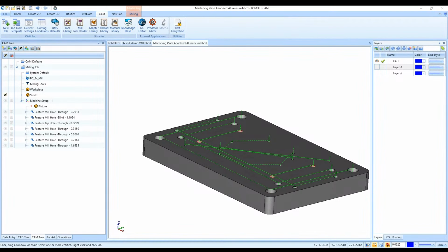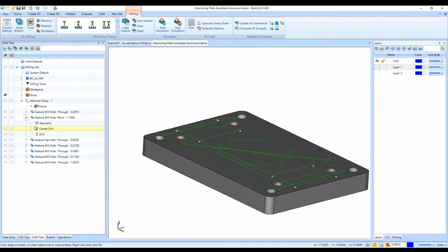Then if we go down to the next step, has a chamfer false. So if it doesn't have a chamfer, then it'll do a chamfer drill for the tapping operations. What this is saying is that even if it doesn't have a chamfer with the geometry selected, it'll still do a chamfer drill operation before any tapping operation. So if I just deleted that one, then it wouldn't have that chamfer drill operation before the tapping operation here.